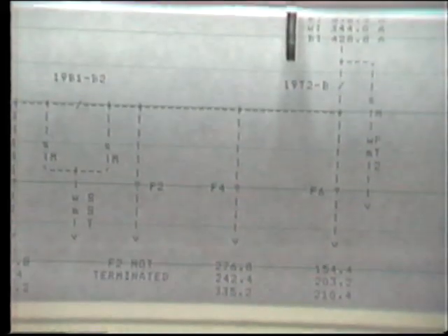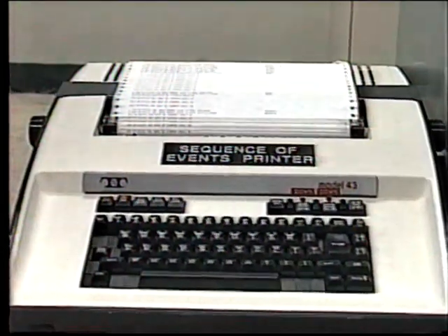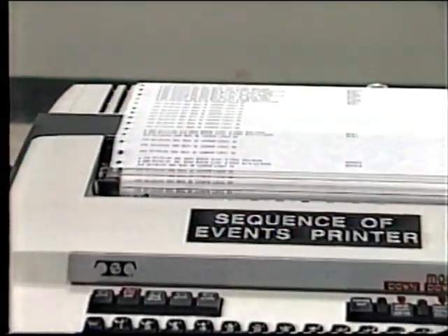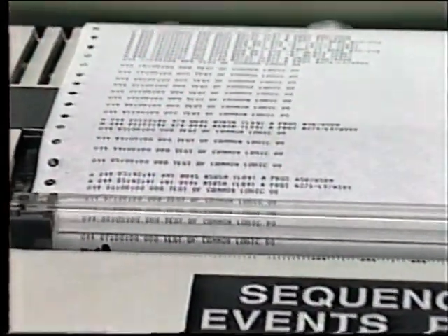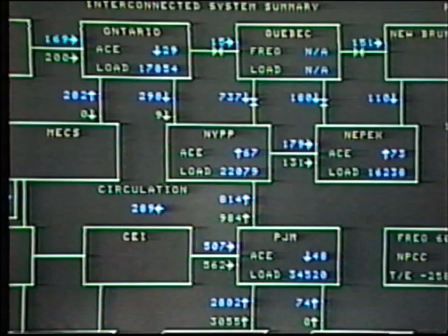Indeed, the central computer is programmed to regularly provide many reports which assist in load forecasting, system planning, and so on. The central computer may also feed information into an events recorder, which is able to print out the sequence of operating events. Information may also be provided for accounting and billing purposes, for example, accumulated megawatt hours, megavar hours, and maximum demand at specific locations.